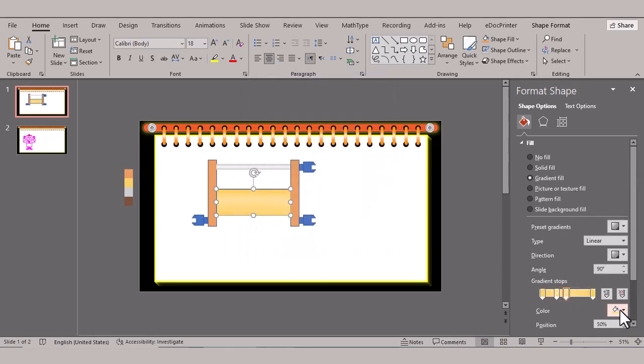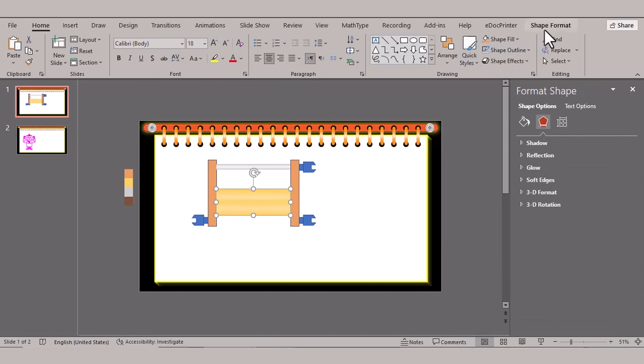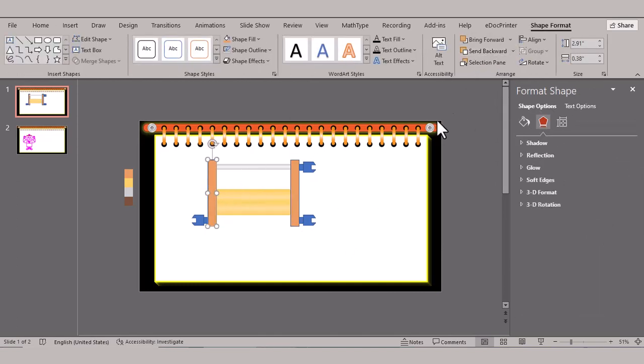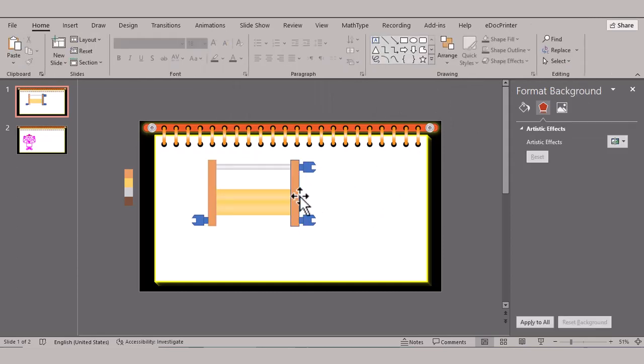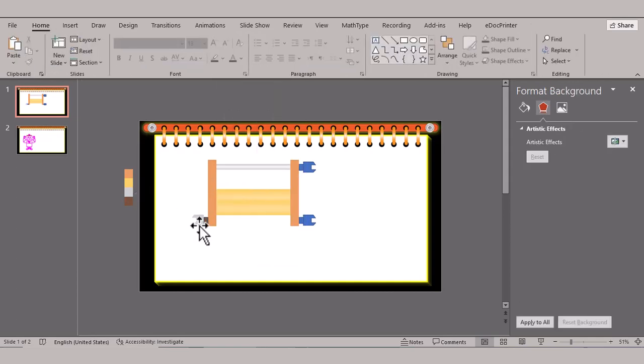Different rheostats have varying maximum power and resistance ratings, stated in watts and ohms respectively. A linear rheostat, for example, changes resistance by dragging a sliding wiper that is in contact with a straight wire coil. Meanwhile, controlling resistance using a rotary rheostat involves turning a knob or dial to sweep the wiper around a U-shaped wire coil. Other basic rheostat types use similar but slightly different methods.